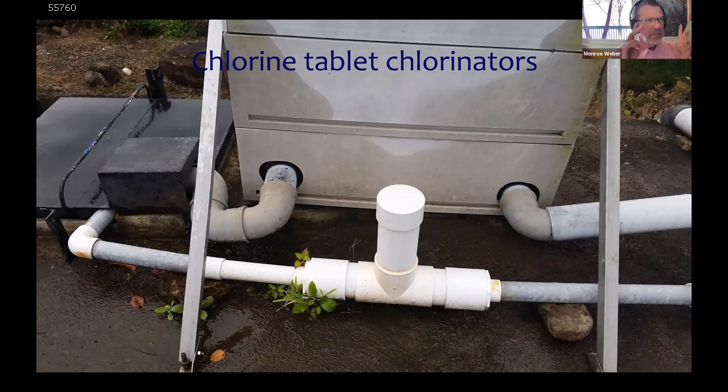And if you get the flow rates right, because you don't send all the flow past the hockey puck, you only send some of the flow that's going into your storage tank past the hockey puck, you can kind of regulate the dose. I'm still waiting to see, someone must have done studies on these to figure out how good they are. This is an option. You can buy this in the US. They're being installed many places on the planet. I've always been skeptical about how good the chlorine dose is as a function of time, but maybe it's not bad because they're being used many places.